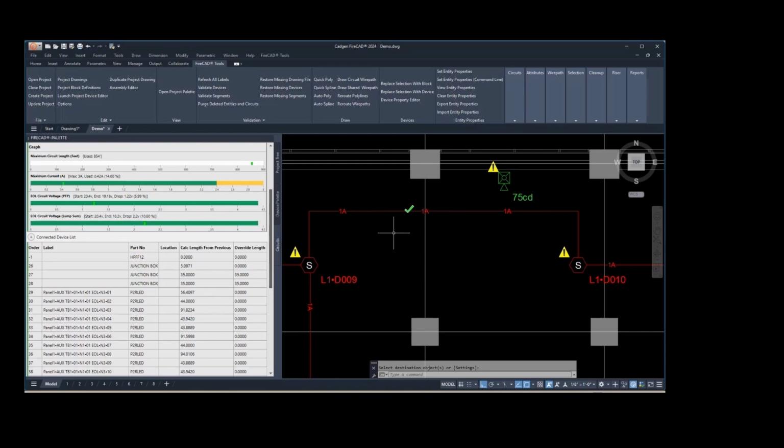Yeah, so it just depends on if all your lines connecting devices on the original job were polylines. Now remember, if you're going to take an existing plain AutoCAD drawing, you're going to have to make sure that the components, devices, are FireCAD recognized devices, as well as the polylines being the appropriate kind of polylines. But you can assign to the symbols, which isn't too bad. It should be pretty quick though. So you just select the symbols that are on there, right?